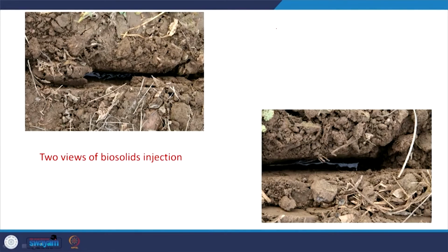So, we looked at different kinds of treatment plants, and in that context we primarily looked at the activated sludge process and the anaerobic process for sludge. So, at least you are aware of those aspects. But we also mentioned from time to time industrial waste that microbes can't degrade, either because it is too toxic, or because of shock loading where microbes are not able to cope, and the structure of the industrial waste, at least pharmaceutical waste, is such that it is not amenable to degradation by microbes within a reasonable amount of time.